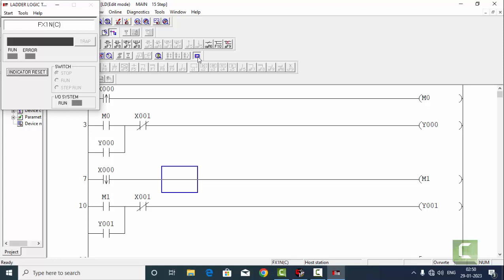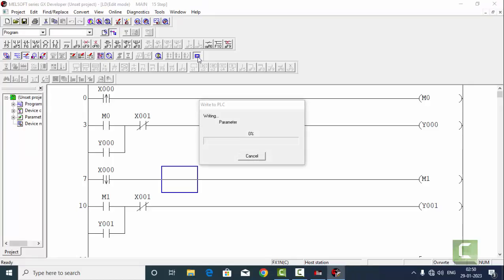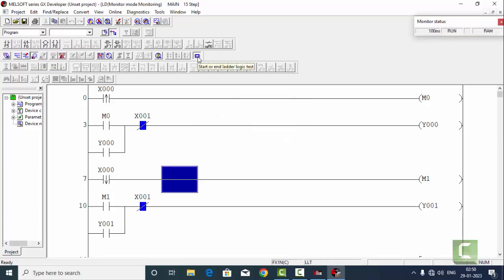Simply, rising edge trigger and falling edge trigger, that particular thing we have to handle, because I'm using lots of PLC programs like Allen Bradley, Mitsubishi, Siemens, Delta, GE, Fanuc, everything. So in different PLCs there are little bit different things. In MicroLogix 500 and all, directly we can take one rising edge trigger block over there, and we have to put the address for that.